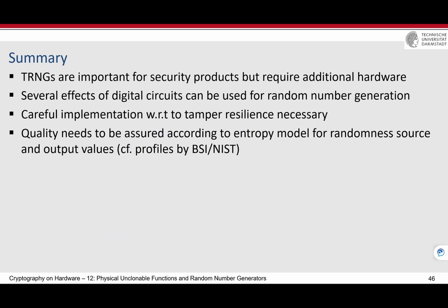As a summary, TRNGs are important for security products, but require additional hardware. Several effects of digital circuits can be used to generate random numbers. I mean, either in the analog domain or the digital domain. And we should be very careful with respect to tamper resistance, because we can easily manipulate a TRNG in a way that the output is completely deterministic and it's always 1 or always 0.